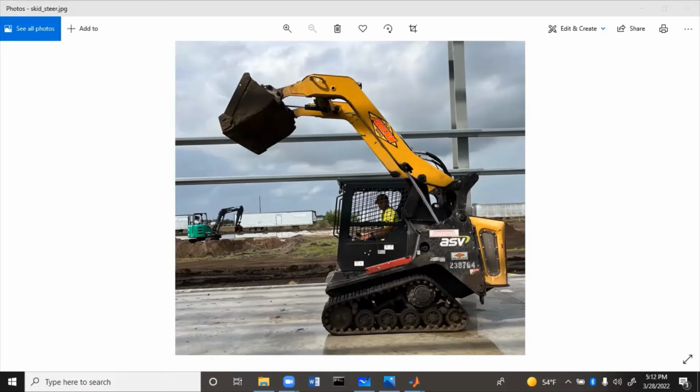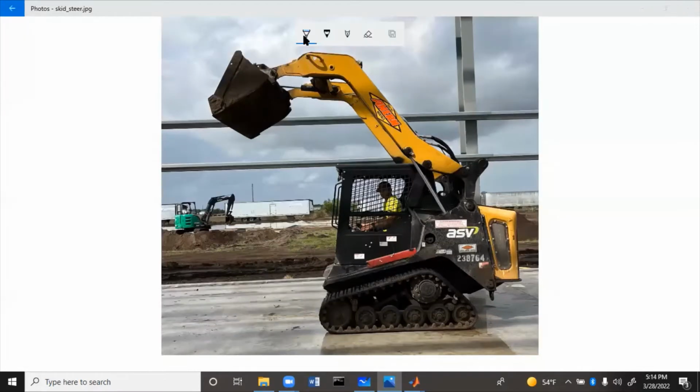That's one of the actuators. The other actuator is what moves the orientation of the scoop. So 2 actuators, 2 degrees of freedom. So now we'll count up links, joints, figure out the mobility, how many loops we need, and then we'll draw out those vector loops. So first we'll draw kind of how everything connects.